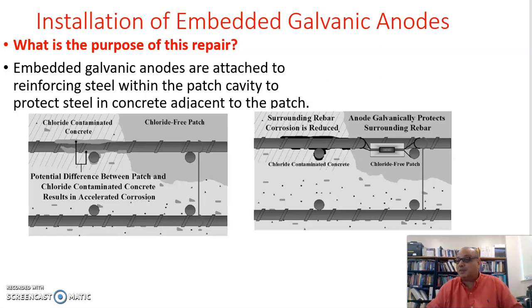To address your colleague's comments: a big percentage of concrete structures are experiencing steel reinforcement corrosion, and that is causing oxidation of the steel reinforcement, which occupies bigger areas, like 4 to 8 times, causing spalling and cracking of the concrete. It's like a cancer, God forbid, in the body of the concrete, and we need to get rid of it. It is hidden within the concrete. It gives you symptoms once things get out of control. You can see that rust, brownish color, coming out. You can see some spalling of concrete.